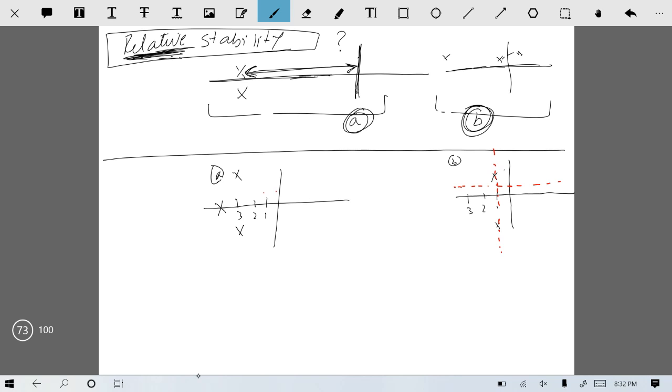Similarly, over here, I have moved this axis to this point and then again applied the Routh-Hurwitz criteria for this new axis for both systems A and B. Now the RH criteria for system B will tell that the system has two poles on the jω axis and it is a marginally stable system. However, the RH criteria for system A will still tell you that your system is stable and it has no pole on the right half plane; it has all poles on the left half plane.